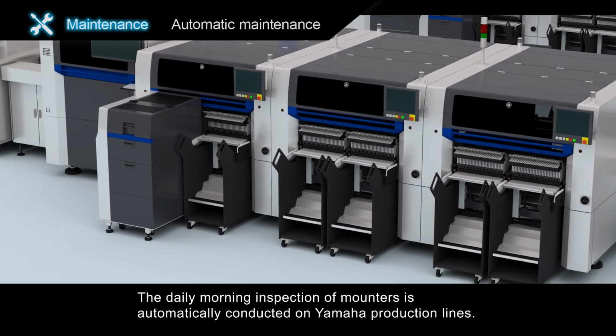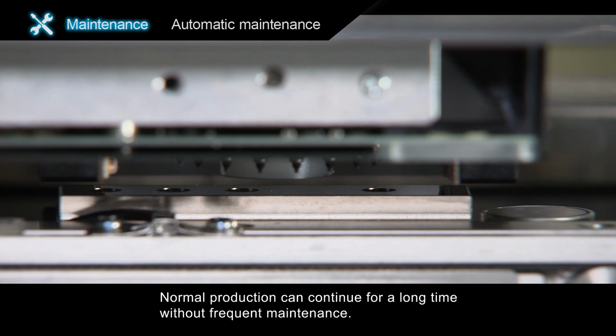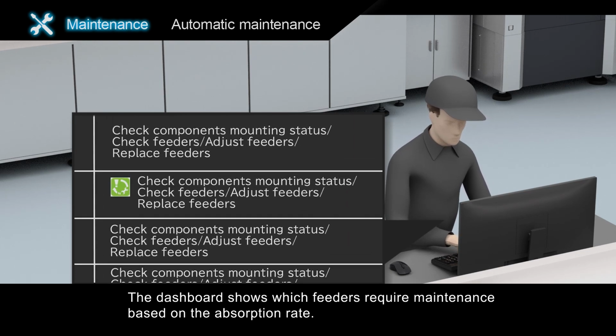The daily morning inspection of mounters is automatically conducted on Yamaha production lines. Tasks such as nozzle cleaning and nozzle tip status checks are performed automatically. Normal production can continue for a long time without frequent maintenance. The dashboard shows which feeders require maintenance based on the absorption rate.